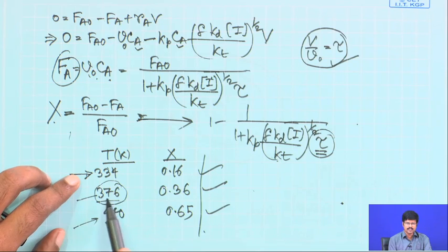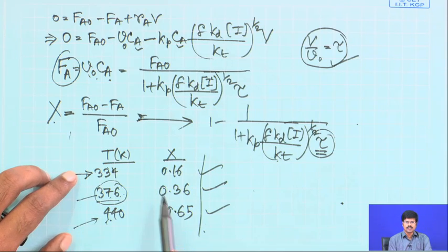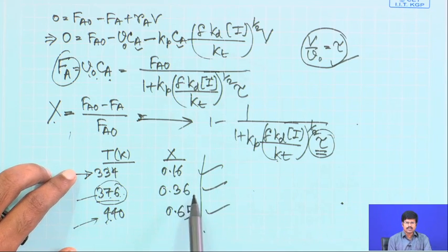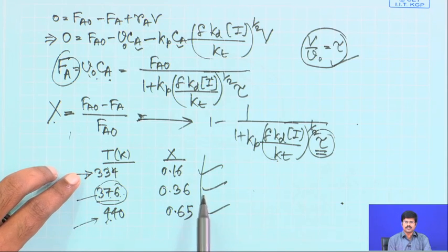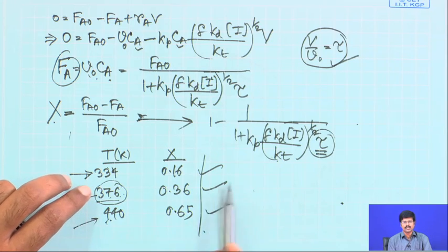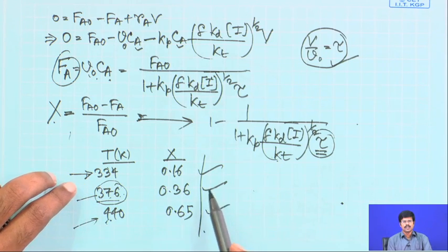Now, typically in this middle steady state if you are operating, you will get say 25% to 30% of the yield per reaction pass. So, if you are looking at that, that will be good enough as far as the industrial grade polymer is concerned for this kind of situation, say radical polymerizations, say if you are doing styrene polymerization.